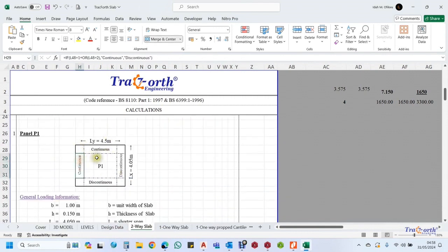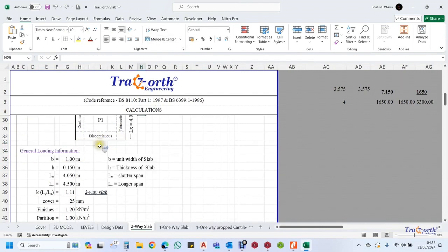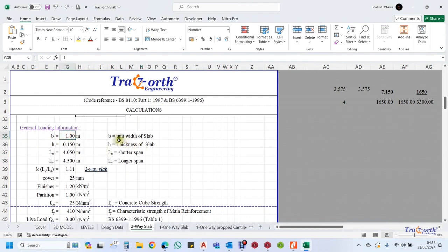So I've prepared this before, so I'm going to be running through to explain. So here we have the width, which is what I explained earlier when it comes to a two-way slab. Even in the design of a slab, the code provides that you carry out the design as though it is a beam. So you have some provisions of the beams that you follow. Then in addition, you have some other extra provisions that cover solid slab.